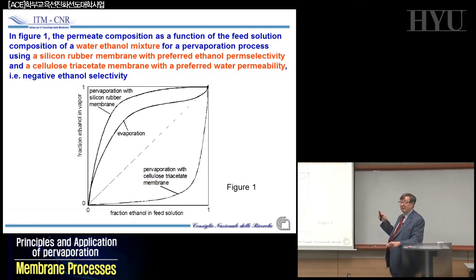When you produce alcohol by fermentation normally, you produce alcohol with a concentration of the order of 12–14%. The microorganisms that today we can use, they die when you increase the concentration too much.